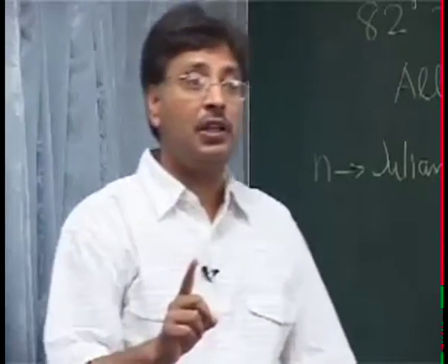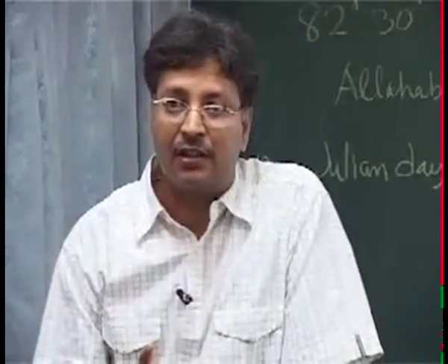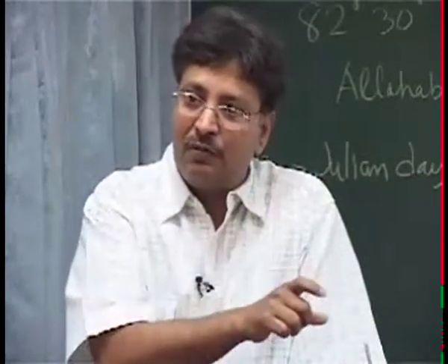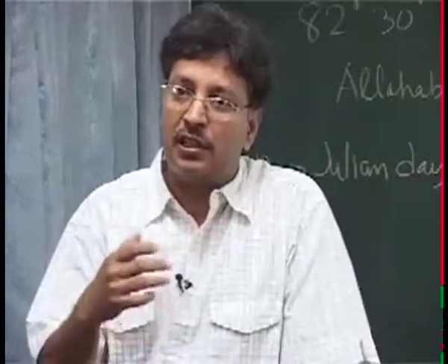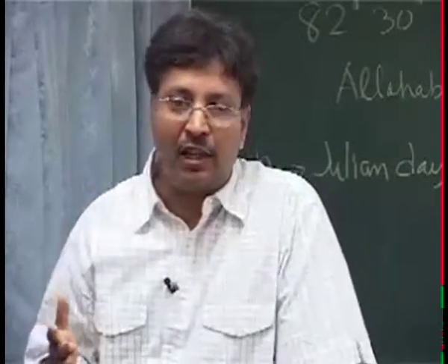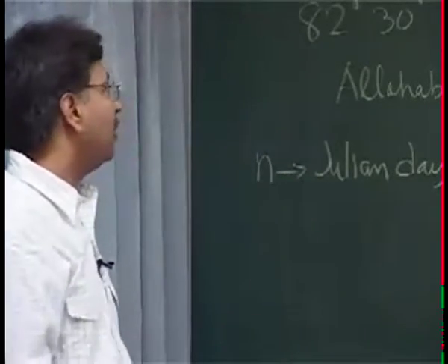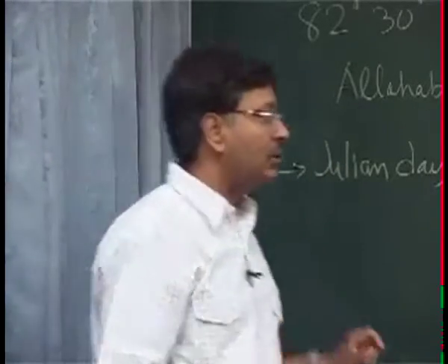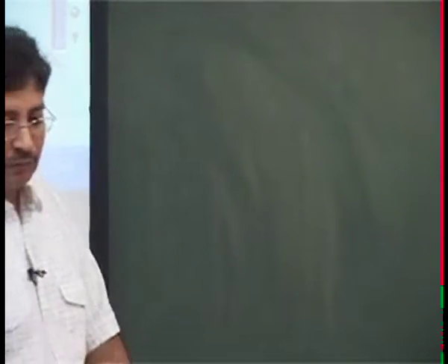The other thing you will need is the surface wind. Okay. This R again you compare with the first table which I gave you, the surface wind which was there, 2 meters and this and that, 6 and things like that. So then I can really find out the stability class. I don't think I should have anything below this, but let's just scan. Okay, see the cloud cover, fine. Okay, this information is enough to calculate the stability class.